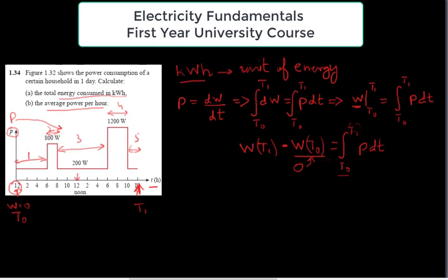You can do it in just the same way as we calculated the current waveform in the last lecture, where we formed a piecewise function for charge and then applied the derivative to it. There is an easier method because you know that energy is the area under the curve of power. So we can easily measure the area under the curve of power over here, and you can see this is the area that we need to measure.